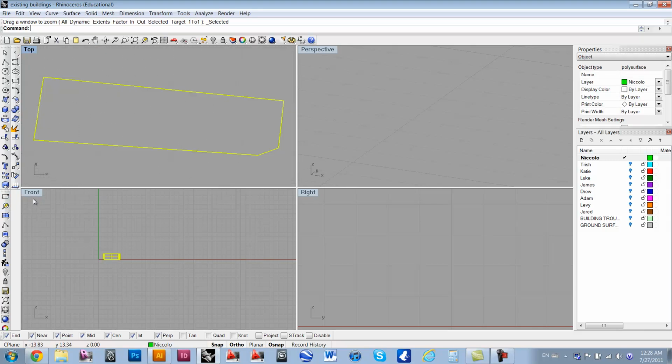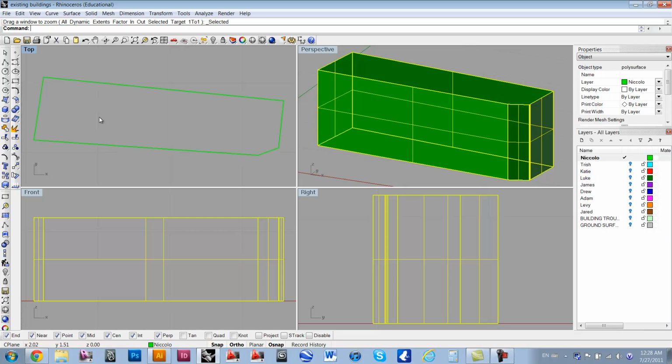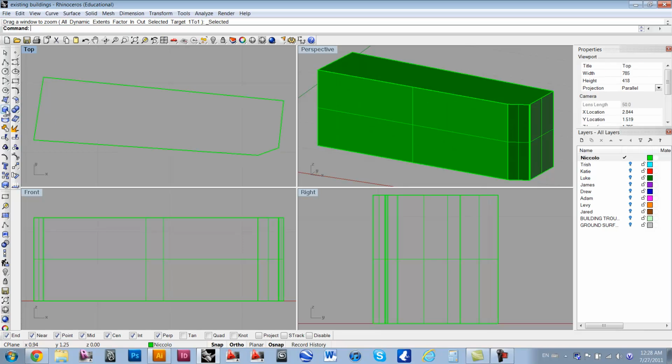When we glue all these layers together later on, we want to make sure that they line up properly, so we're going to create some holes that we'll stick a wood dowel in after they've been printed or laser cut. So go ahead and select your cube volume and pick a point near the end. The dimensions, you're going to type in the @ symbol. That tells the computer to make these dimensions based off of the first point that you clicked.